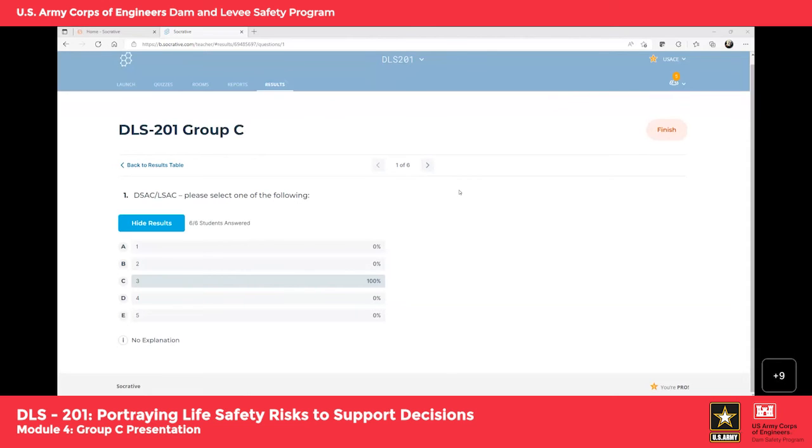When you look at the failure modes individually, they both plot much lower, but when you combine them, you have one with a high AP with low life loss and one with a low AP with high life loss, and then combined, they plot at that 3 range. So is that kind of your takeaway from the big FN plot?